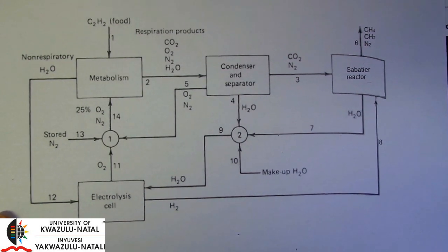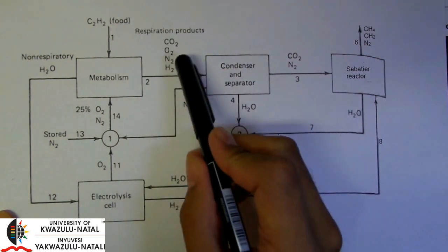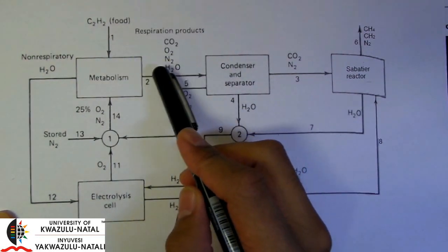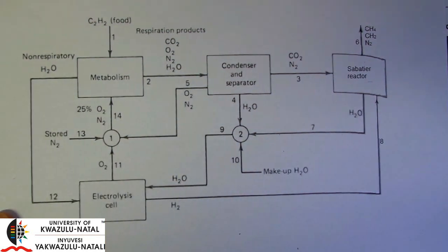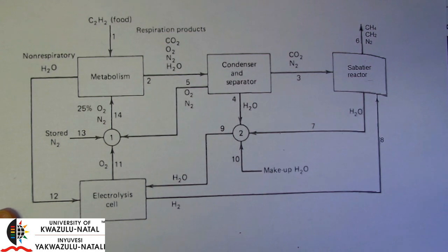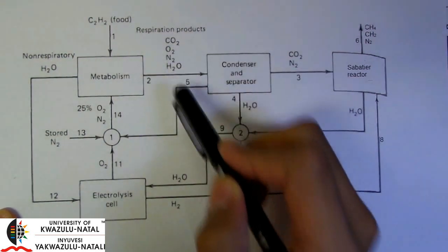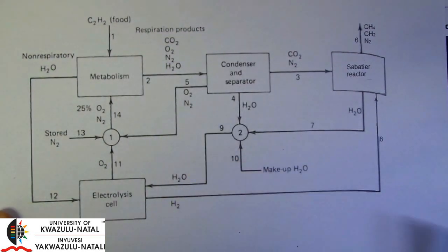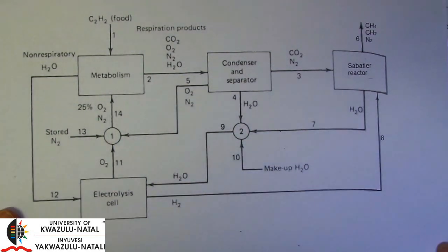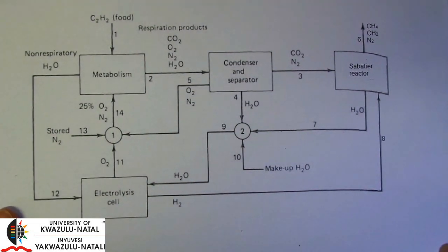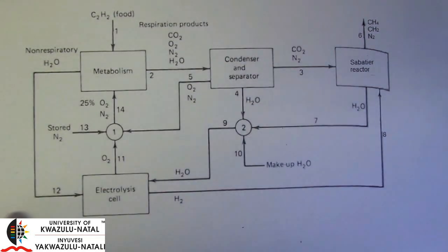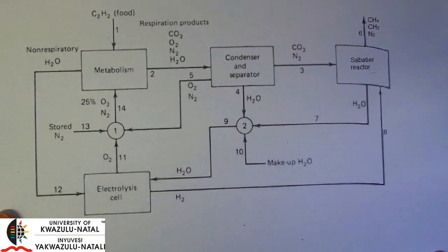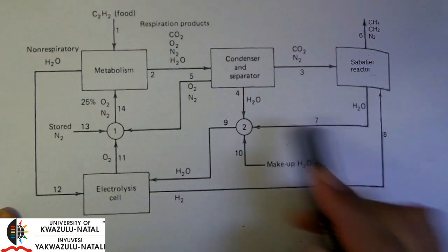And not only that, an amateur's approach would also require us to have many sampling points and continuously take samples and measure them for the composition of various components in our streams. Now, adding in so many flow meters is costly, and also for composition, it's not typically done on a real-time basis. We often have to draw lots of samples to get composition of each stream.